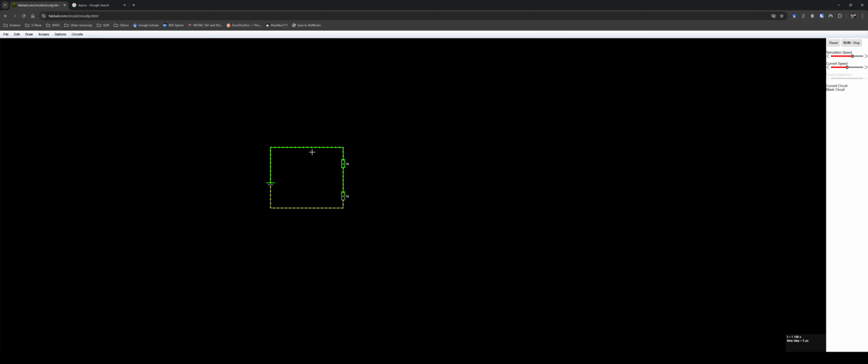The reason for me doing this is that within Falstad, if I add a component without touching terminals like this, it is not going to be recognized. For an example, let's see, I want to measure the voltage. Here I have 20 volts and two resistors of equal resistance, so the voltage should be divided equally.